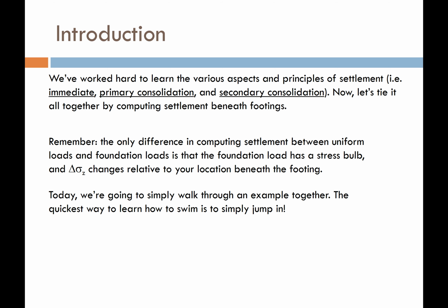So basically this introduction slide is just telling you everything that I just said. We're going to focus on footings. We're going to focus on stress beneath footings. And the only difference between what you guys have already done on your homework up to this point and what we're going to learn in this lecture is that the induced stress, or that delta sigma value, is going to change depending on where you are beneath your load. It's not going to be uniform everywhere because we're not applying a uniform load anymore.